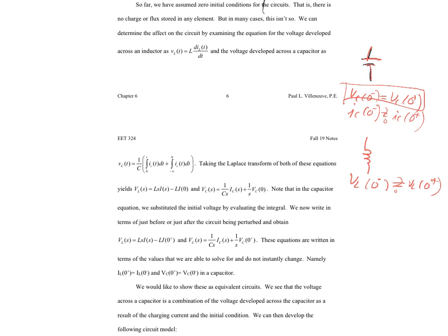So using the voltage approach could be a little bit dangerous and might lead to more work. But we do know that the current must equal the initial charge value. So again, with an inductor, it's much more efficient to model your initial conditions as a current source. So voltage source for a capacitor, current source for an inductor.